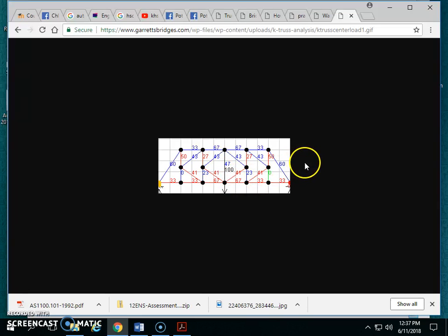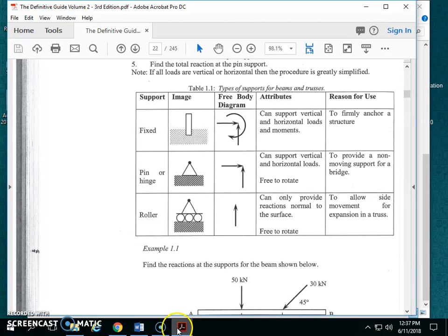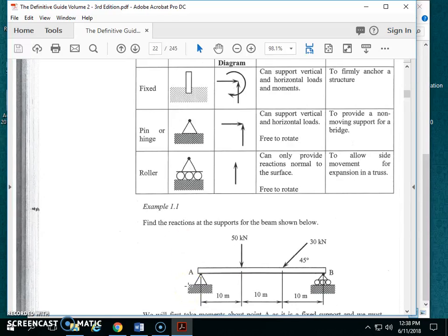The last thing I'm going to talk about in this video, to finish up for today, is that the next thing we're going to look at, before we start worrying about beams and moments, we've already covered moments a little bit, is something called reactions. When we talk about reactions, there are 3 different ways that we can hold a bridge in place. The first way is to have the bridge on roller skates. On either side, it's on some sort of wheel, and the bridge is just allowed to move left and right.